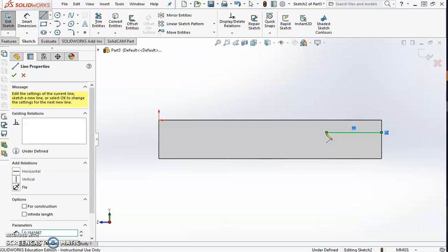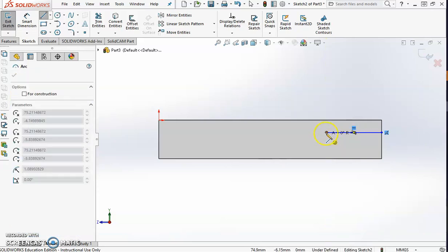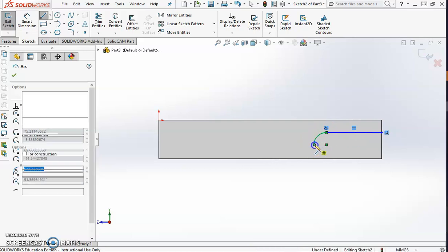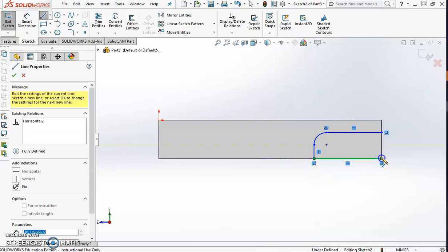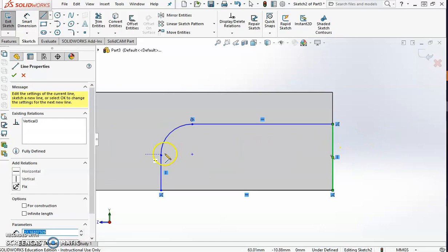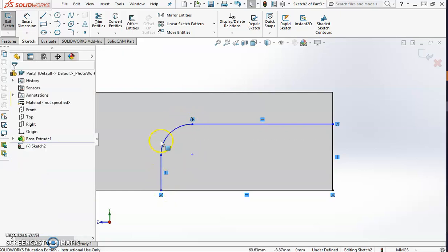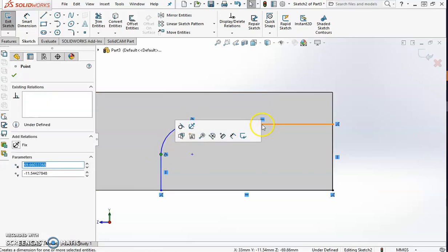So I showed you this technique in another example, but if you move your mouse with the line tool just back over that end dot and then move out, it will actually become the curve tool. Okay, and then I just need to close this off by coming back. Now, if yours did not do that, obviously you could just draw a line over, hit escape, draw a line down, hit escape, and then use your tangent arc. But you're going to make sure that this is tangent on both sides of this. And this obviously needs to be a horizontal line, this needs to be a vertical line. And then I just filled out the rest of the box because we're going to be cutting this corner off.